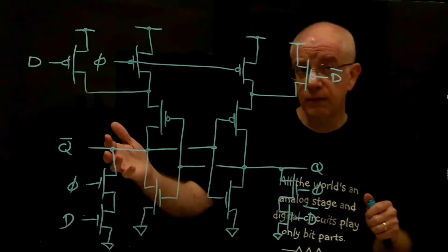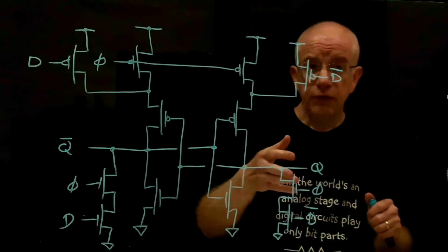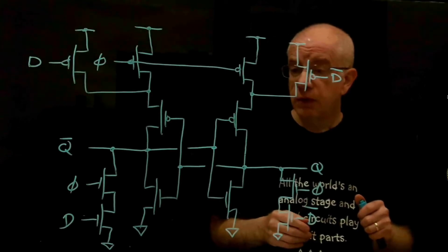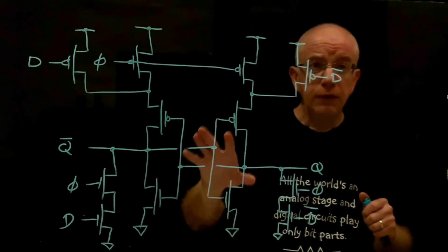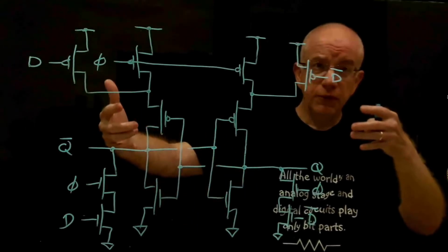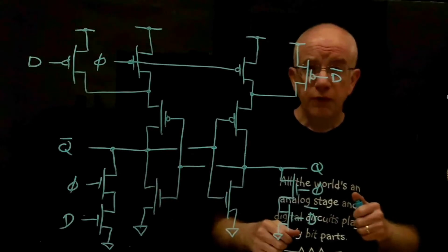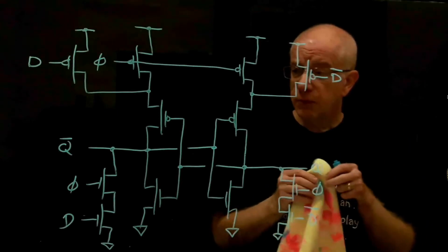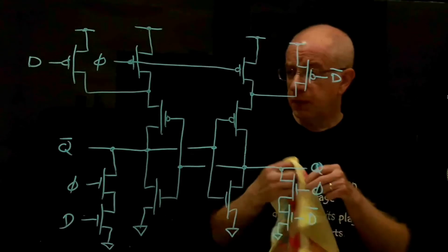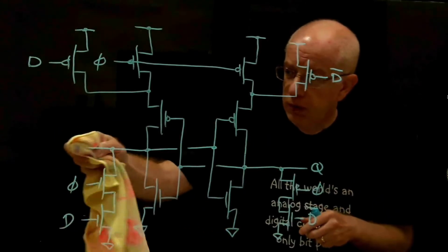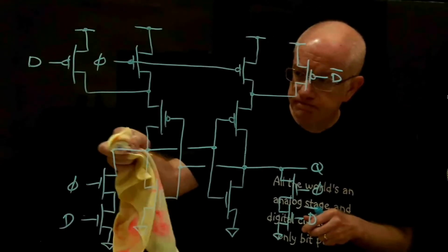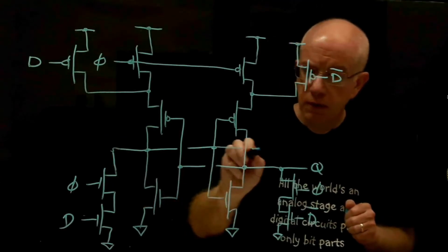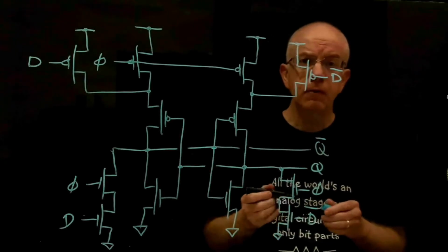So the D inputs come in from one side, and then D propagates to Q, and Q becomes the input to the D stage of the next stage. And as we've laid the schematic out at this point, the D inputs are coming in from both sides, and the Q outputs are going to both sides. So maybe the first thing to do is to rearrange some of those things. And the first part is pretty trivial, because all we have to do to make the Q bar go to the other side is simply make Q bar come out here. Okay, so that's one thing we can do.